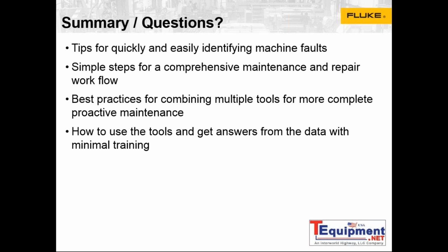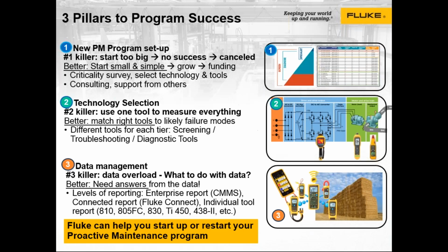Okay. So you talked a lot about vibration, but what if you had a limited budget? Is that what we need to get first, or do we get a thermal camera or some other tool? What tool do you want to start with? That's a great question. So what I would recommend, instead of buying one high-end vibration analyzer or one high-end thermal camera or even one high-end electrical tester, it would be a lot better to get some of the low-end screening tools.